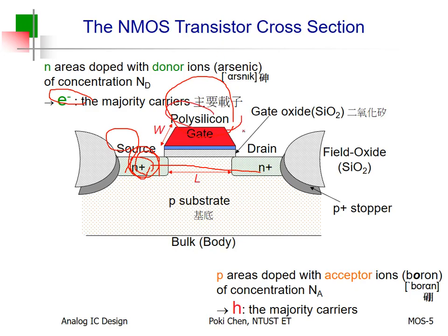Yeah, for the gate, and silicon dioxide in between your gate and your channel. Sorry. From the very beginning, there is no channel for such kind of enhancement type MOSFET. After you enhance it, you can get the channel from nothing to something.